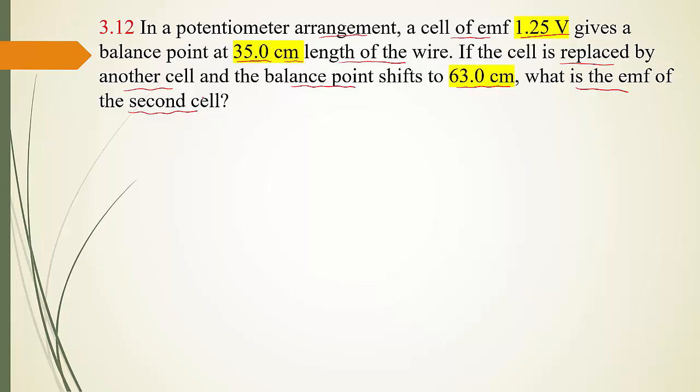Yes, we already studied about potentiometer in our theory classes. You can remember the direct equation we are using. E1 over E2 is equal to L1 over L2. Here, potential difference or EMF is directly proportional to balancing length. E1 over E2 equal to L1 over L2.